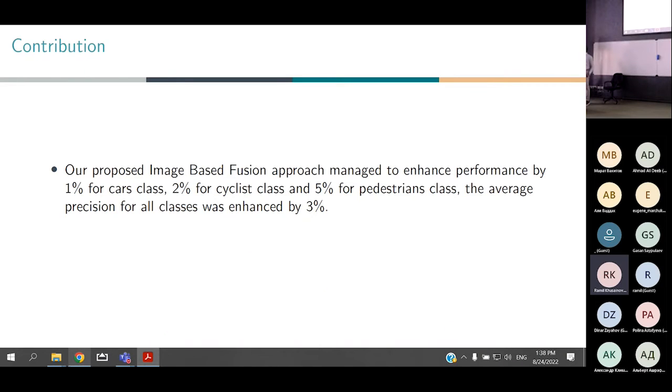Okay. And what about the transformation between lidar and the camera frames? How do you calculate it? For the KITTI dataset, they give already transformation matrices between the lidar and camera. For our custom generated data, we make a calibration between the camera and the lidar to ensure that the object seen by the point cloud is exactly transformed to the image in the same correct frame.